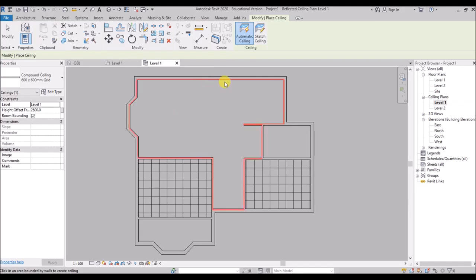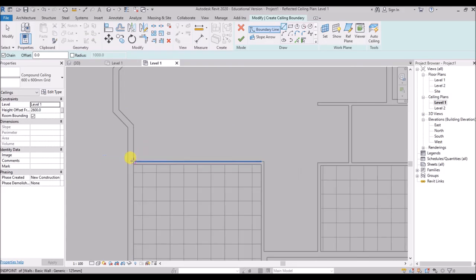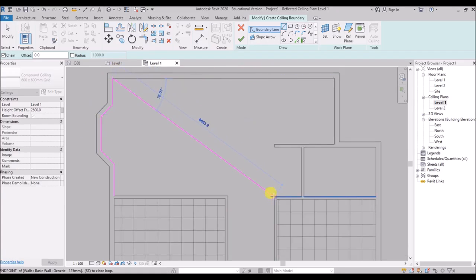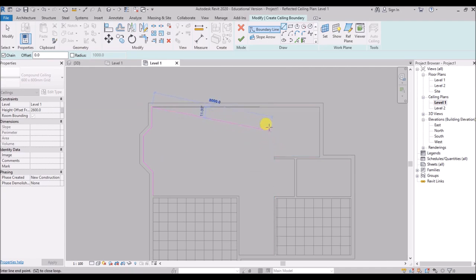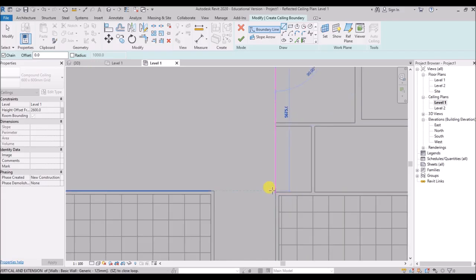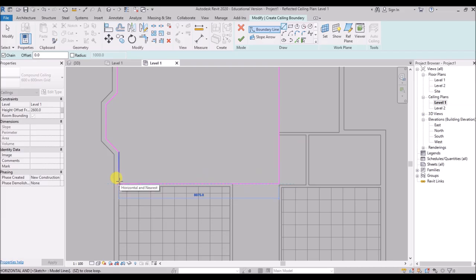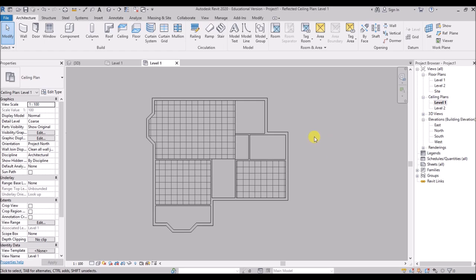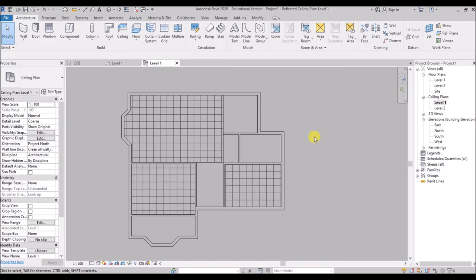Now when I move the cursor here, it takes the complete area. So I'll draw the ceiling here. So click on sketch ceiling and draw the lines as shown. Then click on this tick to add the ceiling. Now I'll fit a few lights at the ceiling.